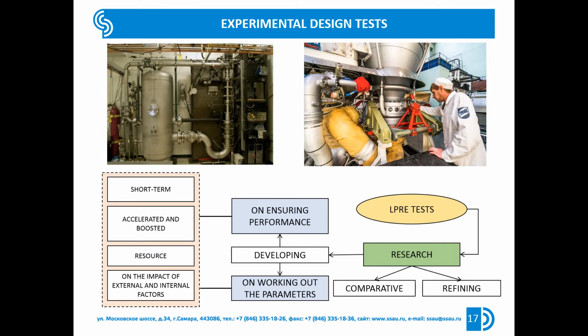Since a large number of external and internal factors have a significant influence on the level of parameters and the degree of loading of the LPRE elements, tests should also be conducted to verify their influence. The types of factors, their combinations and levels are selected so as to create the most stressful but practically feasible operating conditions for each of the main elements of the liquid propellant rocket engine.